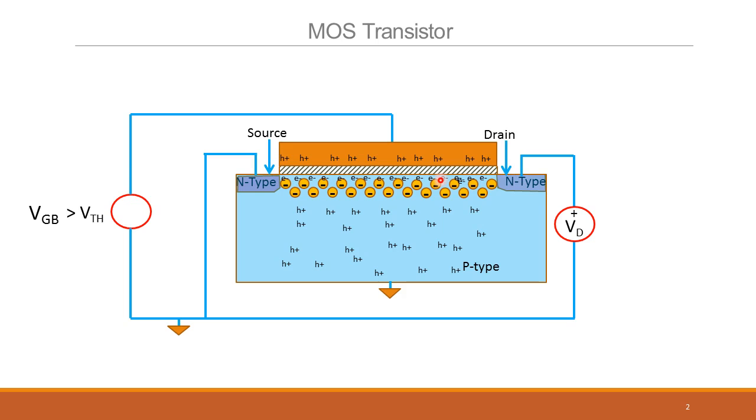This is called the drain because it's draining the electrons from the channel. And this itself is the channel. The inversion region is called the channel because the electrons from the source enter the channel, go to the drain, and then go like this. In effect, the current goes in the opposite direction.